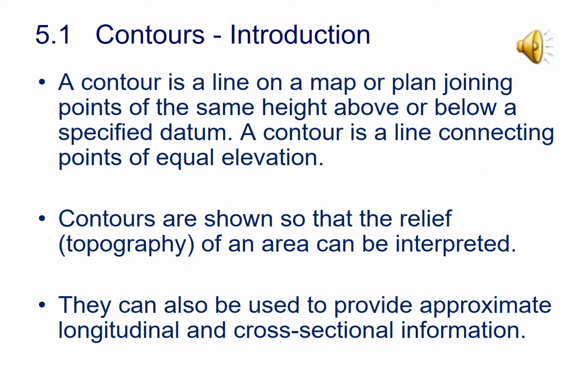So let's start with what contours are. A contour is a line on a map or a plan drawing which joins points of the same height above or below a specified datum. In Ireland we typically use Malin Head, and you'll see on maps where it says MAOD, which is metres above ordnance datum. The contour is the line connecting the points of equal elevation above that datum point.